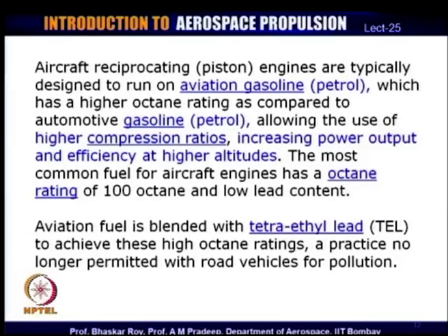Now, they have, as I mentioned, a very high heating value, that is how they are chosen, and quite often they are to be used under high compression ratios. We need to have high power output, and of course, as we have just seen in the efficiency definition, good efficiency at various operating conditions of the aircraft, and most specifically at high altitudes where the aircraft actually flies.